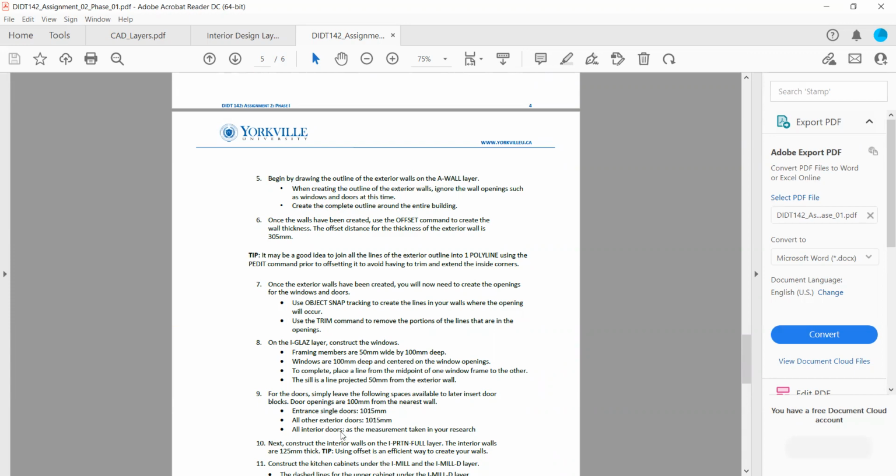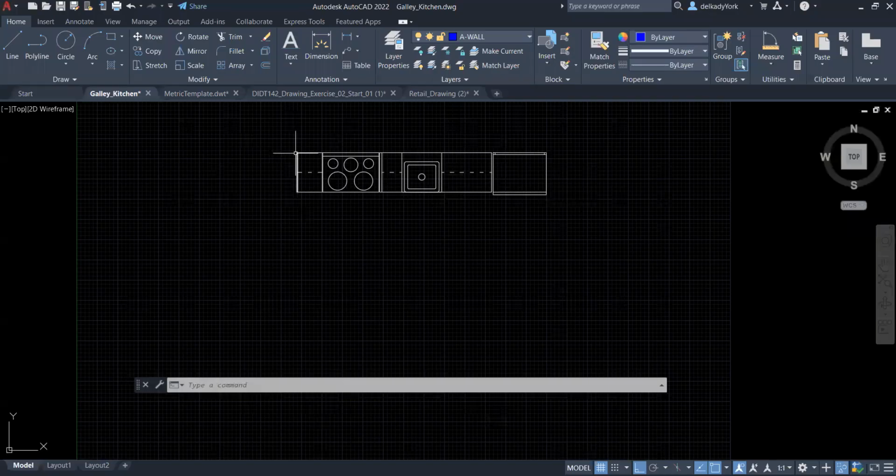I am here going to be using, for my exterior wall, which is going to extend from here to here, the number that came in, I think is 305, as the exterior load bearing walls. And then we're going to have two wall partitions here that are going to be 203. All right, so the first one that I will be creating is this.